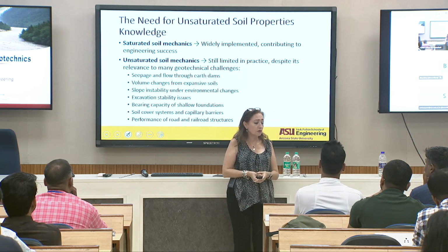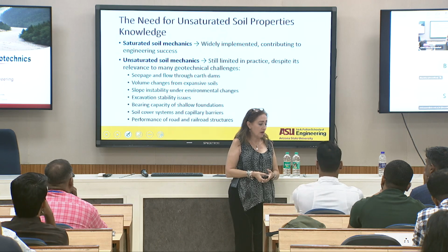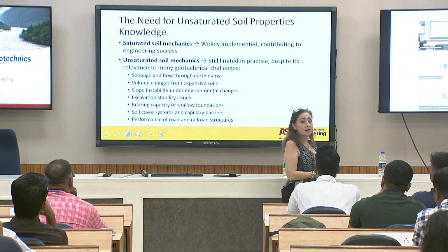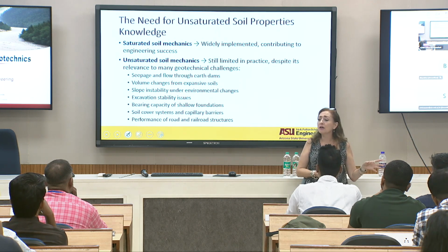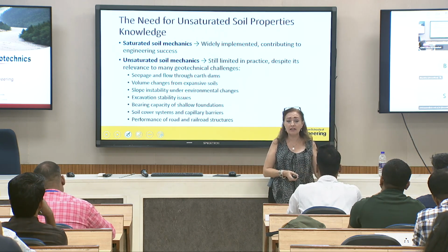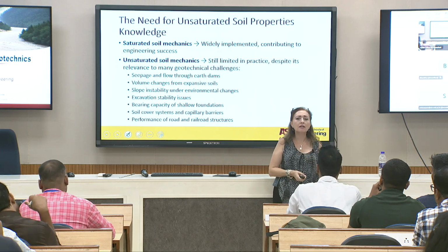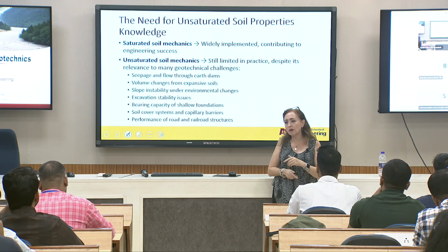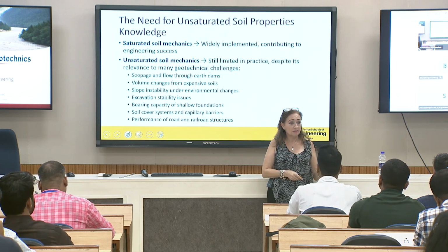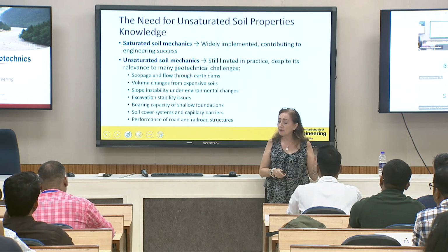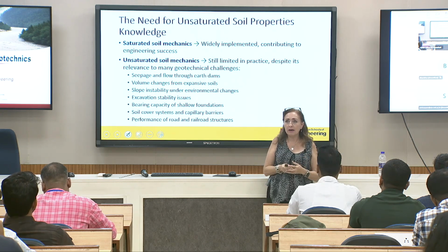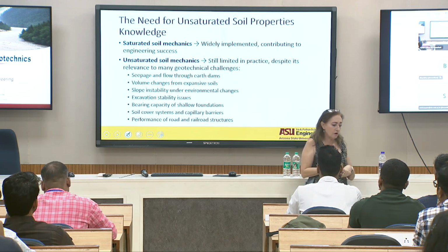Just to name a few, the seepage and the flow through earth dams is one of them. Volume changes from expansive soils, and actually this is how unsaturated soil mechanics started in engineering, right? We were only paying attention to expansive soils, and all of the conferences available were conferences for expansive soils. Thus, that was the only way that we talked about unsaturated soils, the moisture flow, and the problems with the volume change due to the moisture flow.